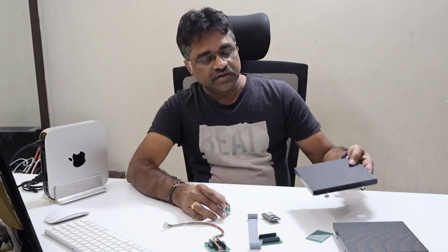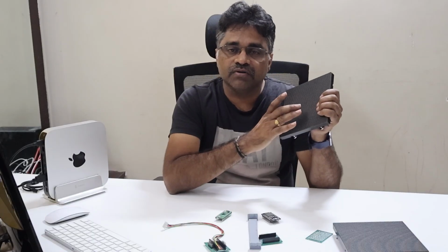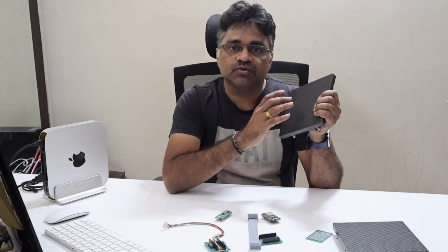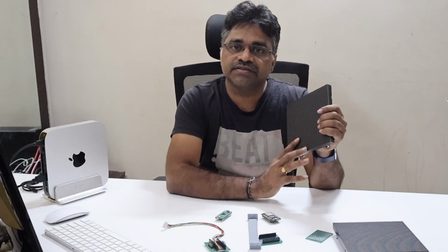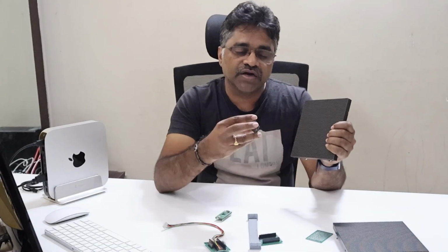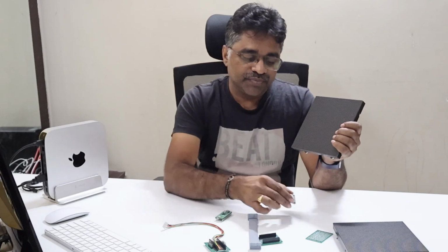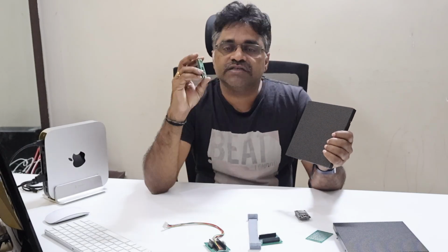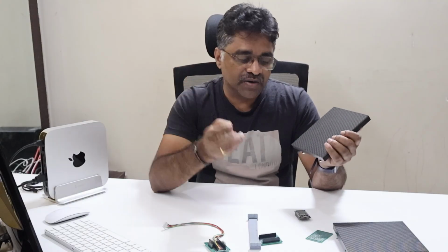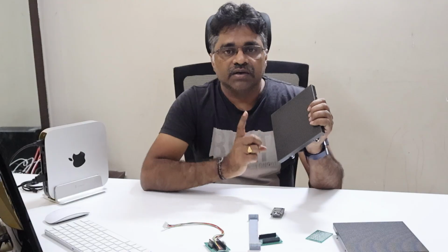The panel has to be continuously refreshed, for example at 60 Hz, 120 Hz or 280 Hz, whatever refresh rate we want to drive. That process I can offload from the ESP32 and put that logic into the Raspberry Pi Pico. It will not make any burden on the ESP32, since the ESP32 is not directly driving the panel.